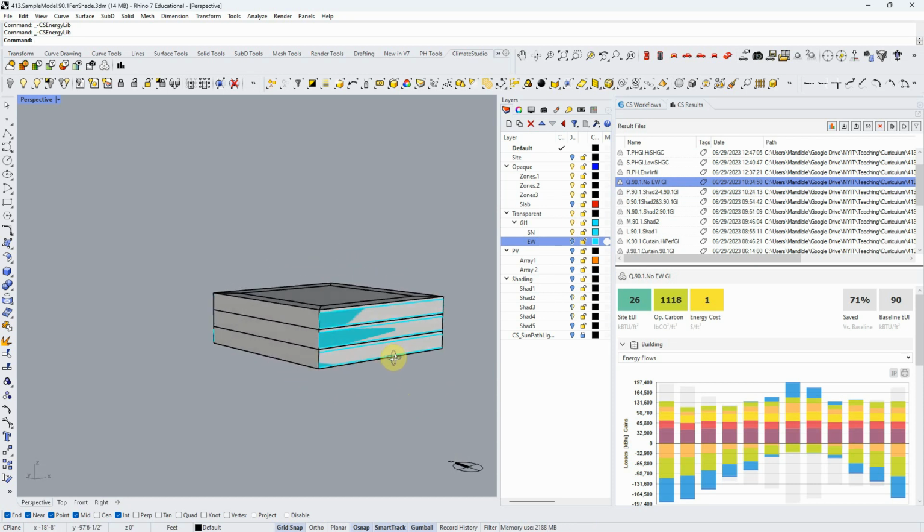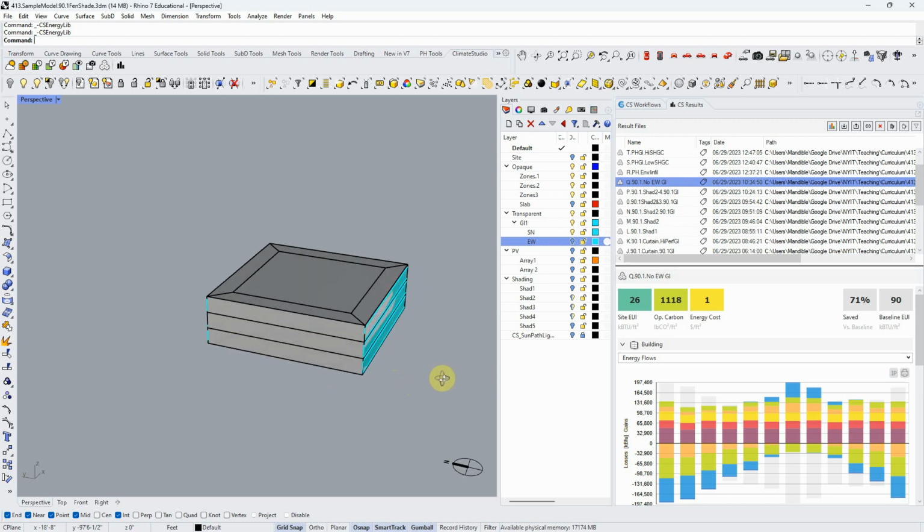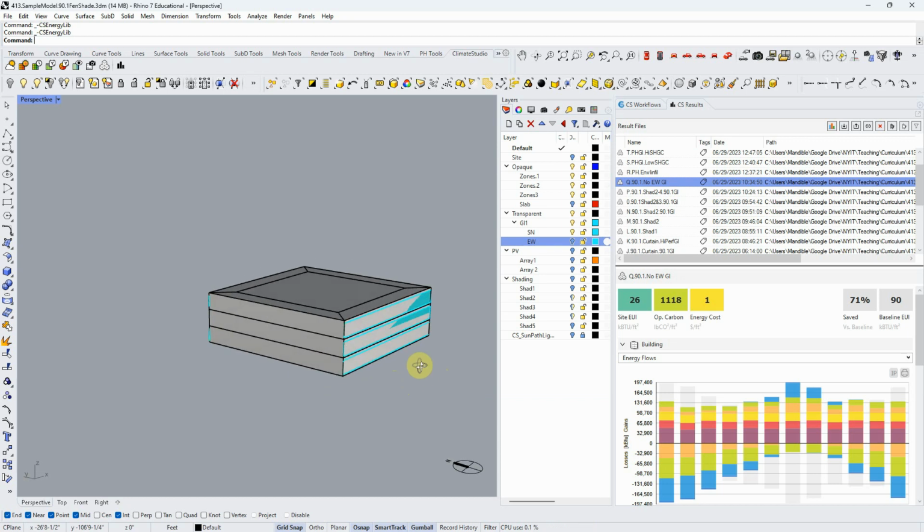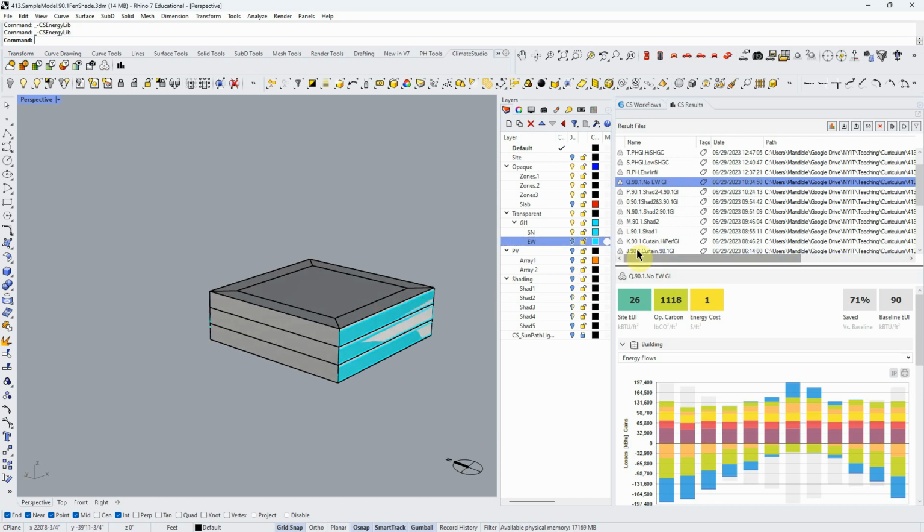Now I think this is about at 40% glazing. That's window to wall ratio. 40% is the maximum in code actually. So whenever you have a curtain wall that has more than that, you have to do an energy model to establish that it meets code from a performance standpoint, not a prescriptive standpoint. Something else I can talk to you about if you want.